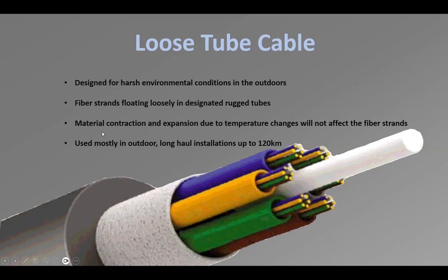Oh, wow. Material contraction and expansion due to temperature changes will not affect the fiber strands because of the way it is constructed. Why is it not going to affect that? Well, because they are inserted loosely. They have a lot of playroom here. Plus, they are also filled with a thixotropic jelly that is also going to provide some reactive cushioning to the environmental changes, mostly temperature.